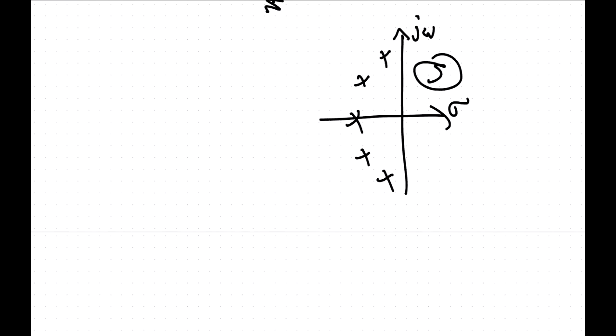If you're sitting up here, your feedback stops, because you have no gain. So you essentially open-loop your amplifier if you operate up there. So you've got to be sure that you sit within that range. Because how much gain does a preamplifier really need to have? It just needs to, yeah. So I was like, maybe if you put a whole lot of negative feedback, maybe it won't be so bad. But I don't know.